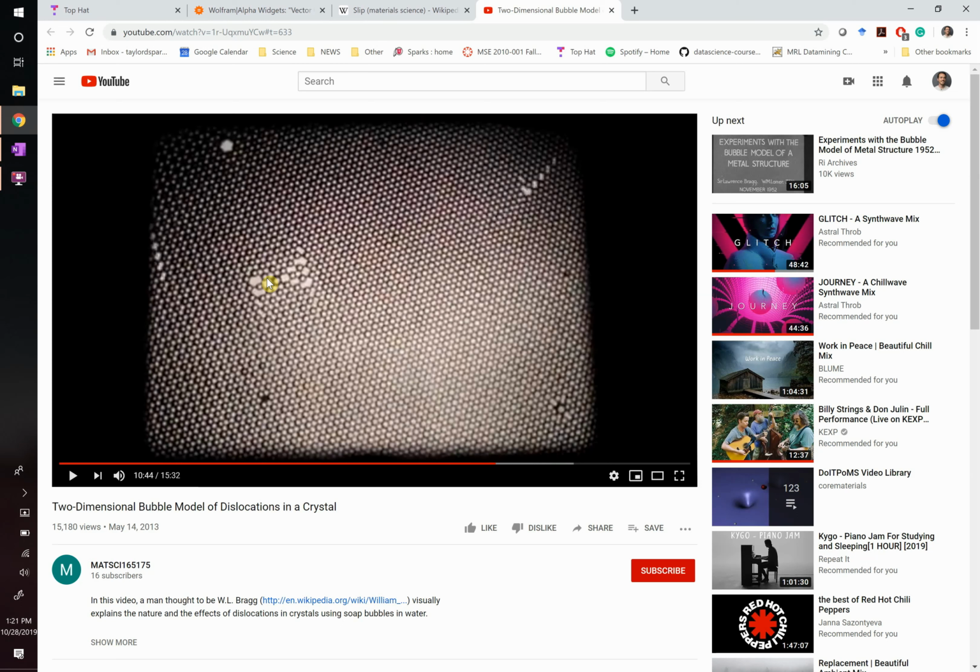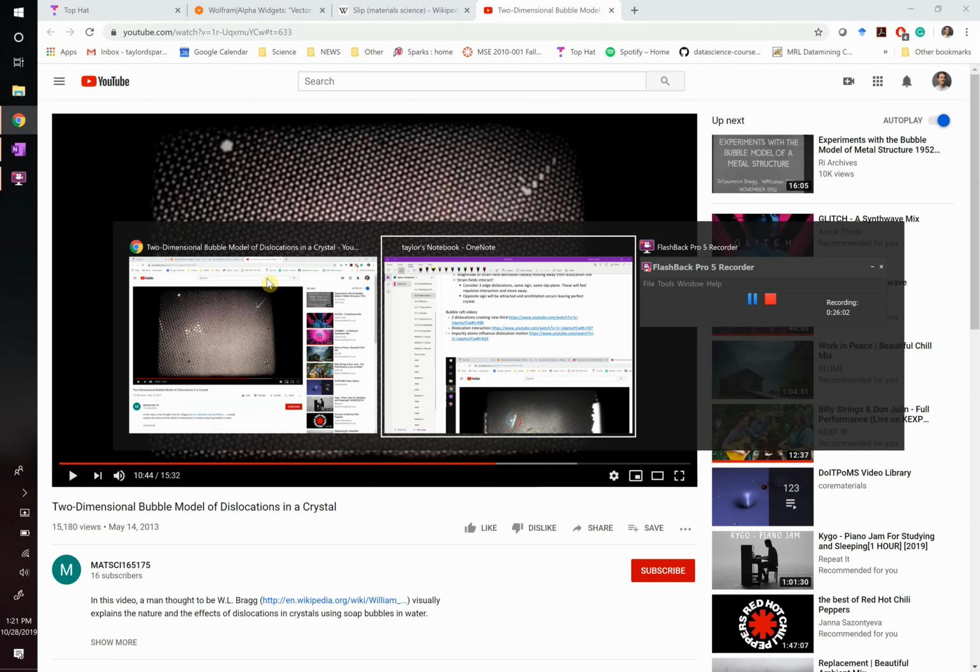They make sterling silver, even though copper is a cheap material, because sterling silver is a better alloy: it doesn't scratch as easy, right? You replace some of the expensive silver, which is nice, and you add something that strengthens the material so it doesn't scratch as easy, and it's because of dislocation pinning. Okay?